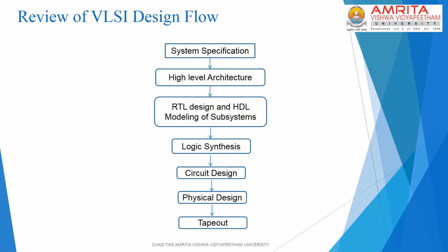And the output of the design flow in the tape out phase will be all the files which contain the layout details of each layer in the design. That means there will be files corresponding to the diffusion layers, metal layers, the poly layers, and so on and so forth. So these files are represented in a standard format like GDS2 or CIF, and in this format they are handed over to the foundry for further processing and eventually being fabricated as a chip.